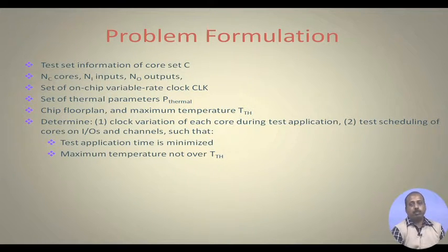Maybe if that maximum threshold is say 85 degree centigrade, we will try to operate within say 75 degree centigrade, being pessimistic that in actual operation, the actual testing session may become about 80 or so, but still in that case we have got a guard of 10 degrees, so that this DTM is not invoked and the test session is not stopped in between.